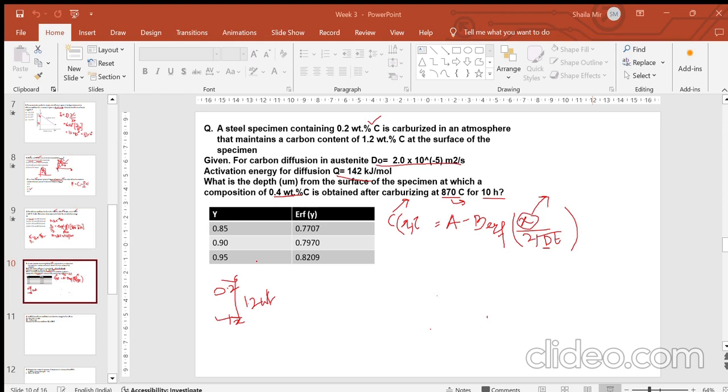C, is it? Tie lines connect points with the same temperatures. Right. So actually, the option about maximum and minimum temperature is wrong, specifically because tie lines are drawn at a constant temperature. So they have nothing to do with the minimum and maximum temperature. The option that they represent the composition of two different phases is wrong because we cannot say they are in equilibrium, two phases. That is also not right. So tie line connects the points of equal temperature in the liquid and solid phase is the right option.